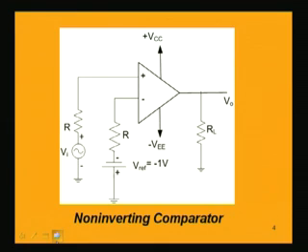So, now let us take such an example having a negative reference voltage. We are again taking this example, but with a reference voltage of minus 1 volt. If we have minus 1 volt as reference, again we will be considering that sinusoidally varying voltage Vi, and we have VID equal to V1 minus V2. This is V1 at the positive terminal, V2 at the negative terminal. But here V2 is a reference voltage which is negative, that is minus 1 volt. So, ultimately it will become V1 minus (minus 1 volt). That means it is becoming V1 plus 1 volt.